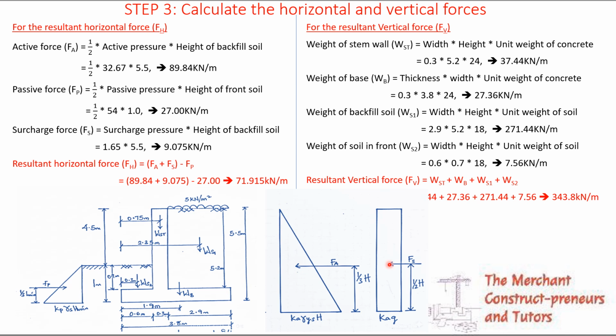This is the surcharge, and this is for the soil in front of the wall. So the stability is based on these forces, trying to balance these things together, right? So let's take it one after the other. Active force, that's on the active side there, Fa, is given as the shape of this triangle.